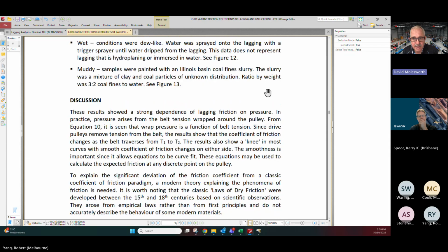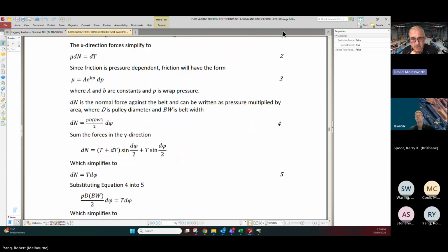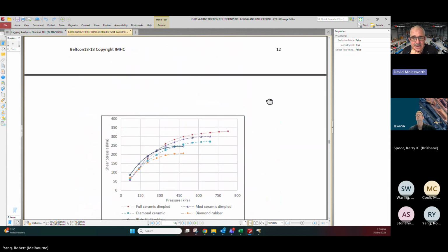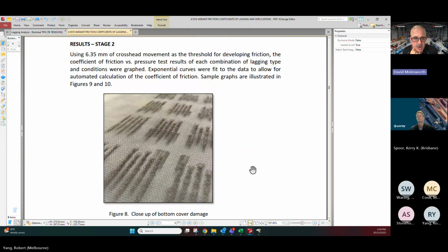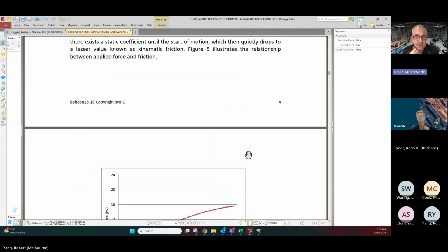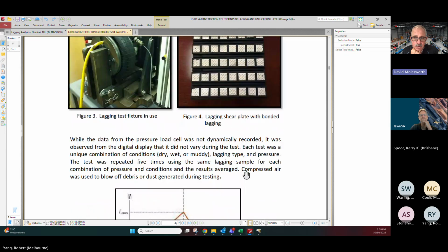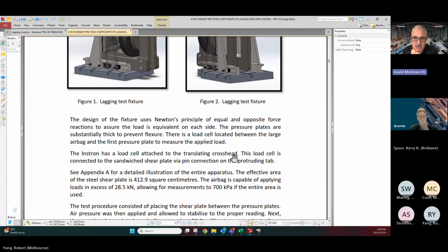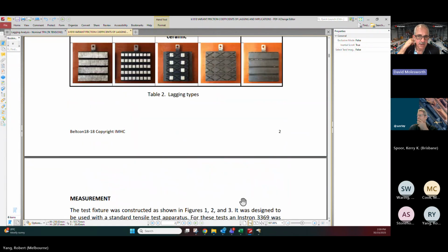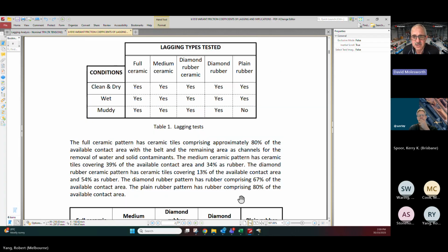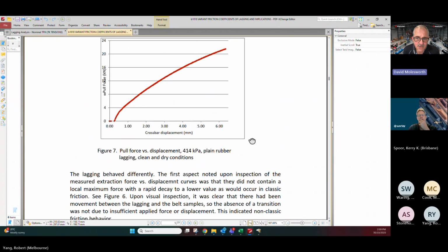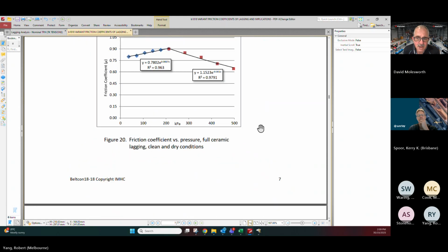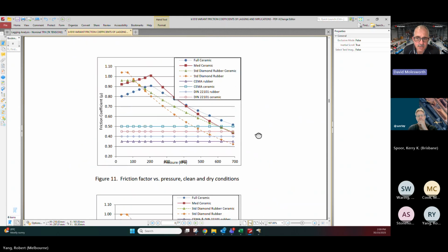The way that fatigue one came about was we provided the CAD models of all of our lagging to Conveyor Dynamics. We then provided all of the dynamic physical properties of the rubber, things like Poisson's ratio, Young's modulus, the shear crack resistance, I mean, just all the physical characteristics. And then that was put through an FEA analysis to determine the fatigue life.